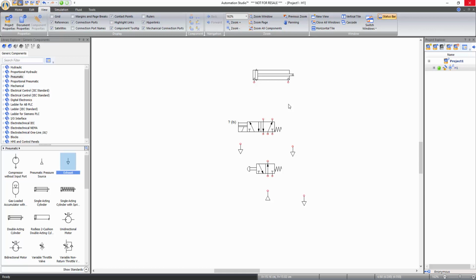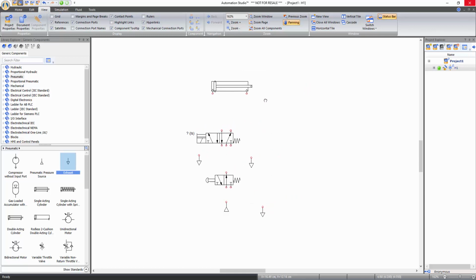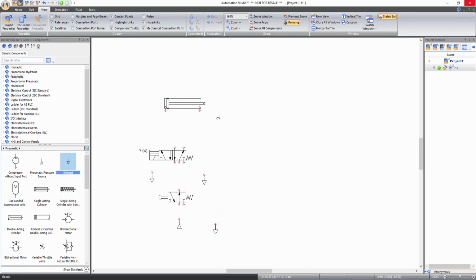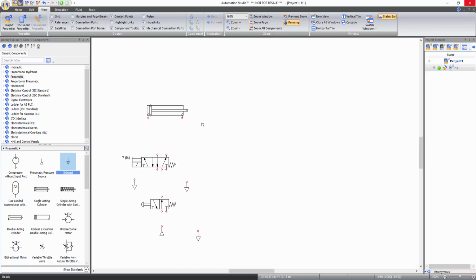To pan the document, click on the panning function of Zoom tools. When you click on the panning function, the cursor transforms into a hand and then you can pan the document by holding the left mouse click and moving the cursor. Alternatively, you can press and hold down the spacebar and move the cursor to pan the document. To disable this function, just right-click on the document.